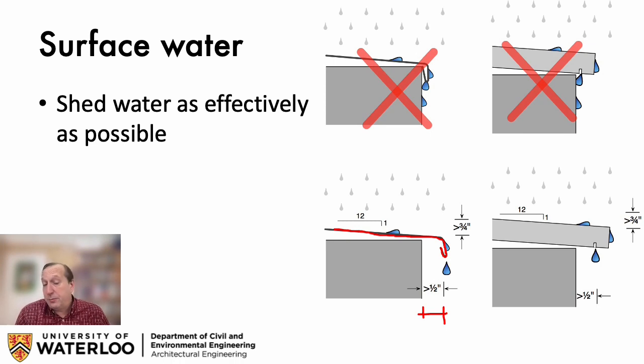And that ideally should be shown on drawings to make sure that there's no surprise that we're expecting the windowsill to collect the water and shed it off. On the bottom right, you can see that we have a masonry version, and rather than bending the metal, we make a saw cut or kerf, K-E-R-F, in the stone or concrete. This can be cast into concrete or cut into concrete or stone, but it's making sure that water droplets reach an interruption and then drip free.